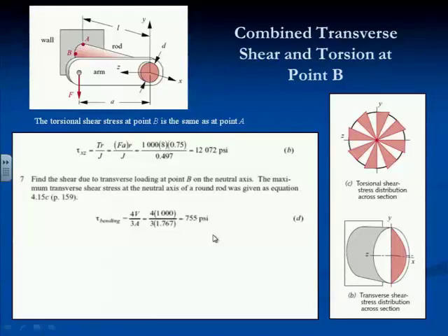Why is that? Well, if I have the same load, whatever this was, 1,000 pounds, and I double the length of the beam, does the shear diagram change in magnitude? Still 1,000 pounds. It goes twice as far, but the number doesn't get any bigger. Does the moment get bigger? Oh yeah, it doubles, right? So if the beam is long, the moment dwarfs the shear. But as I get shorter and shorter, at some point, they're not going to be so different.